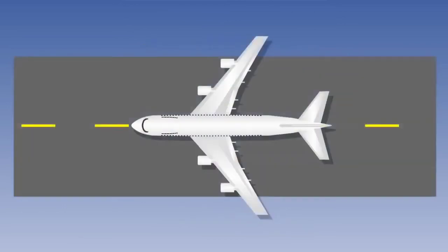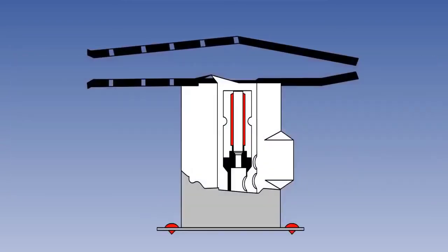It is also necessary to measure air temperature on the ground. A factor affecting takeoff distance and the takeoff power required is temperature. A reduced power takeoff may therefore be possible, and this is a valuable operational consideration. Without forward movement of the aircraft, air within the sensor casing can stagnate. Stagnated air could give a false indication of the outside air temperature.